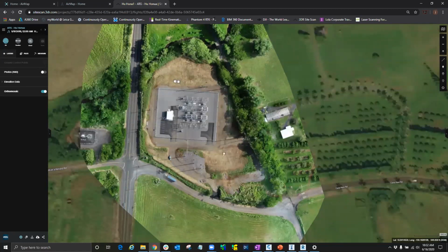I see a whole bunch of questions here, so we'll go to some of them. Jeremy's asking, do you fly all surveys with an RTK drone, or are you able to get accurate information with the regular Phantom 4? So yes, we've done a handful of flights with RTK, which is great because you can just sign in to one of those stations to get that information. But you can get extremely accurate data without using the RTK.